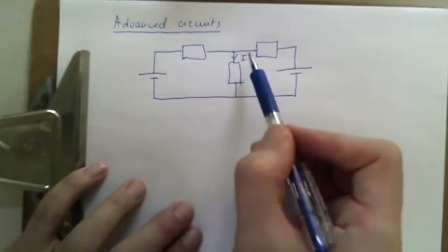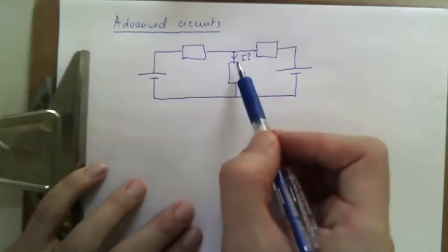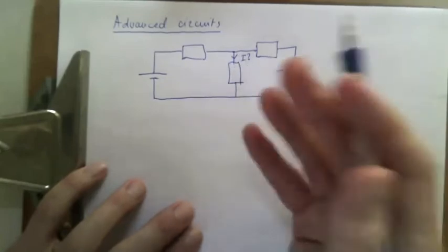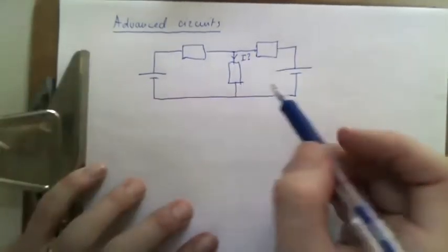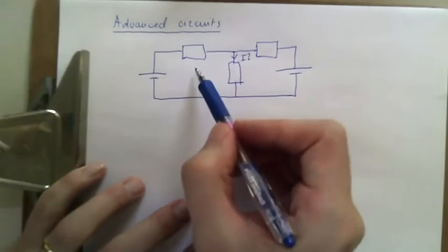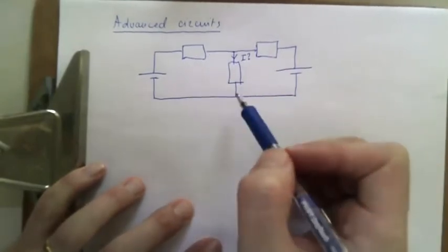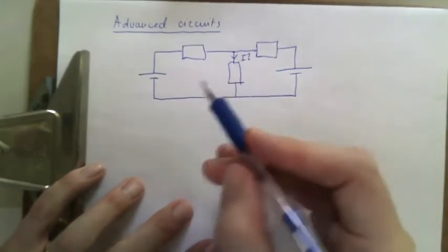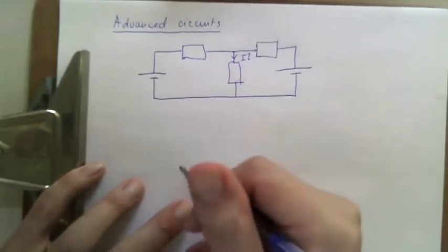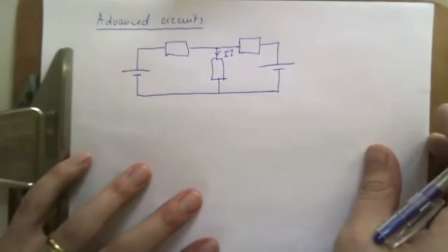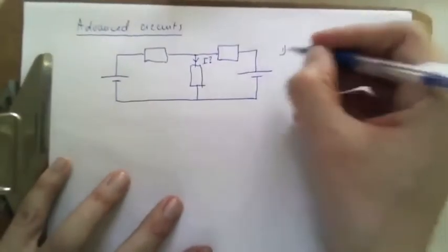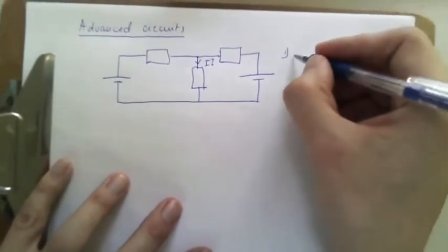So it's entirely possible that if you have these two currents coming together, this current would be going down. So I'm taking a step ahead and saying it makes a lot of sense to expect something like this. But now, how would you solve this? There are two rules that you use to solve these circuits. Rule number one is charge conservation.